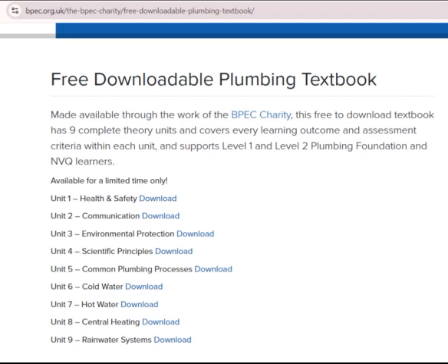Before we investigate these systems, we will look at some of the key phrases and terms you will come across as we work through the wet central heating subject. Low pressure heating: a heating system that operates at temperatures below 100 °C, because it includes an open vent pipe. Open vent: the open vent prevents heating systems from exceeding 100 °C and assists with accommodating the expansion of water due to the water being heated.